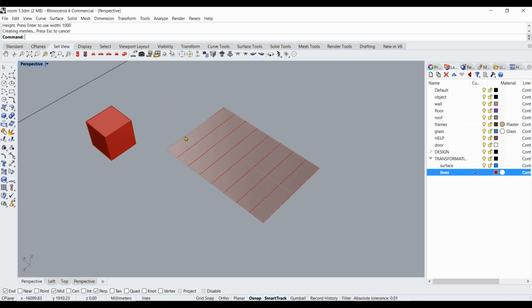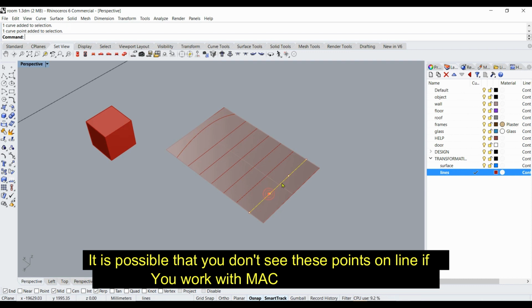And I would like to keep the first lines straight, and for example these ones, I just hold shift, I select these points, and you know, I would like to move them, but I don't have to touch exactly these points. I only use my reference cube, and I say, well, I'd like 50 centimeters, and then it goes up, and I'll do something completely different here.